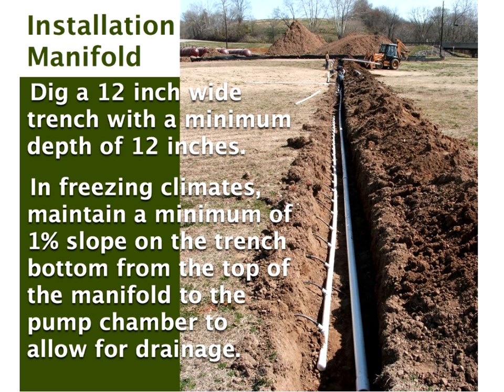You shouldn't get a biofilm buildup inside the emitter. My company uses tributyltin maleate, which is a bactericide compounded into the material of the dripper. And our competitors use a compound of arsenic, which they compound into the dripper. Both of us do it, obviously, especially for wastewater. So that should be more than adequate to prevent a biofilm building up inside the emitter. We can talk about biofilm building up inside the tube, but I don't want to make this an advertising presentation, so read our literature.